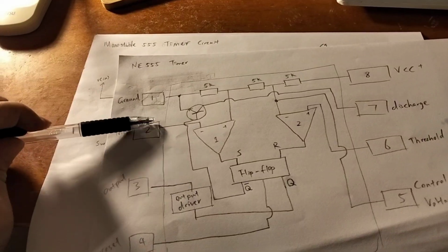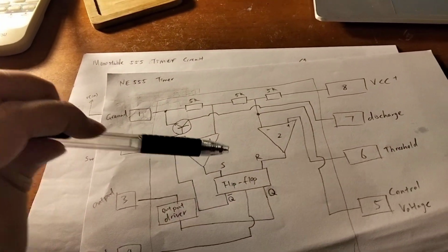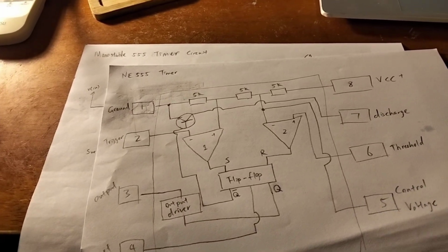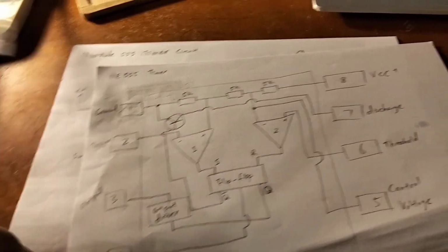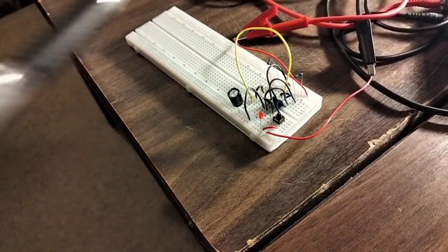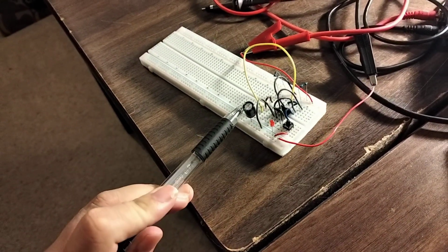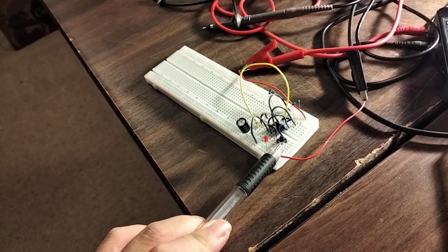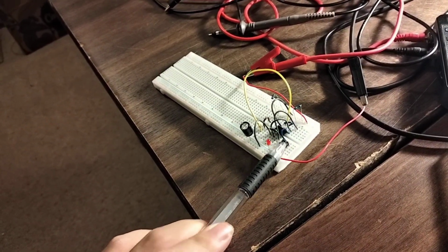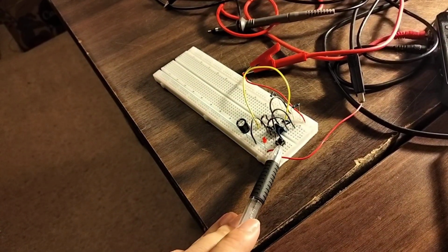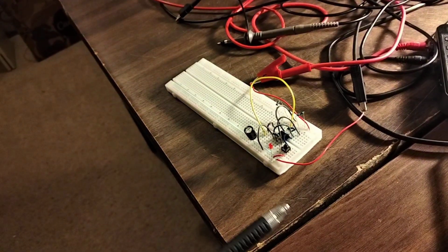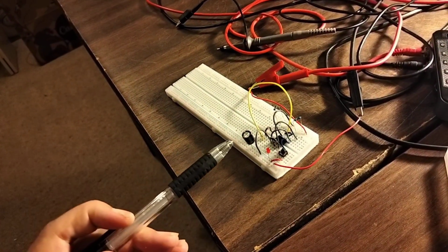We have to basically set a state on the flip-flop and then wait for the capacitor to either charge or discharge to set another state. So essentially, when I press this button, on button down, it immediately sets the state of the flip-flop such that the output pulls high. And then when I lift my finger off of the button, the circuit is designed in a way such that the capacitors take time to reset the state again.